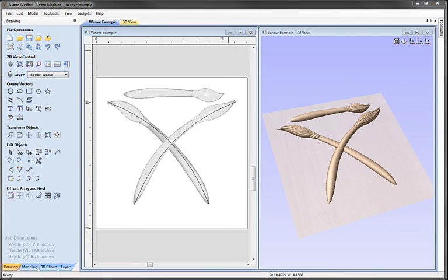So that almost concludes our detailed look at the extrude and weave function. You've seen what a powerful and flexible feature this is, and although it's only a single icon, how the shapes you can create with it are very varied. We looked at how we could start by creating something very simple by taking a vector cross section and extruding that along a vector drive rail. We looked at how we could introduce multiple cross sections in order to make a more complex shape, or even use closed drive rails to start to create borders.